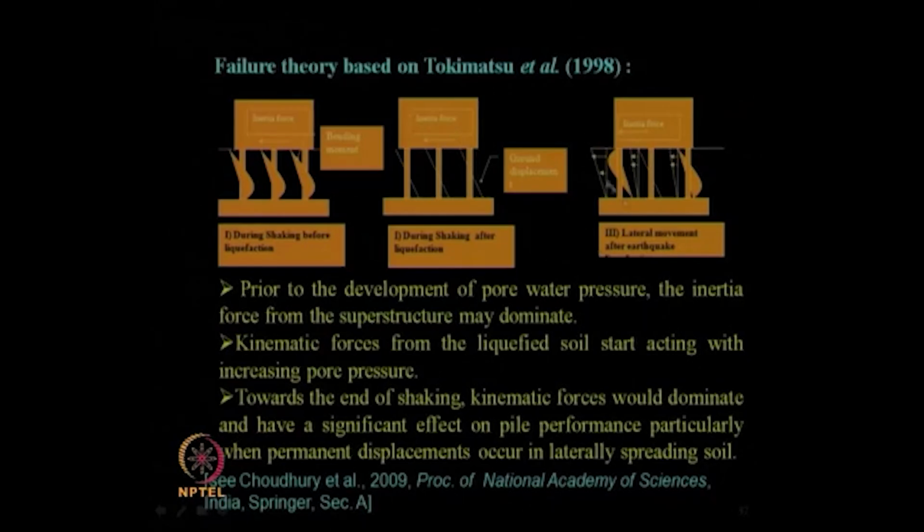So, what will be the combined effect? Lateral movement after earthquake and liquefaction will be something like this. It will have the bending moment due to the extra lateral load from the earthquake, as well as extra bending moment due to the ground movement from the liquefaction of the soil and movement of the soil. Those aspects need to be considered, which are discussed over here.